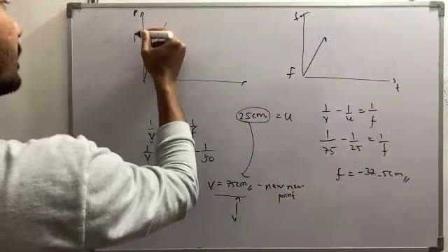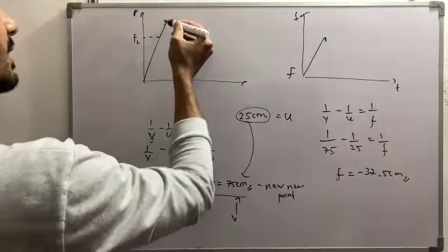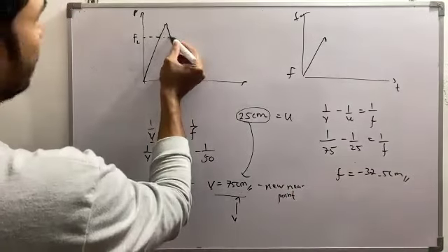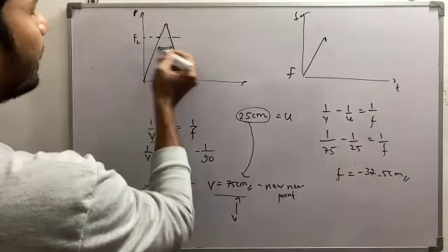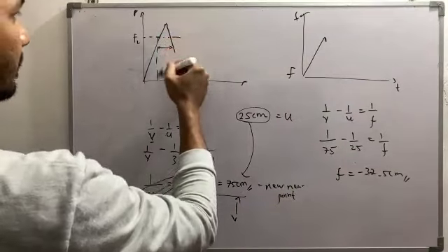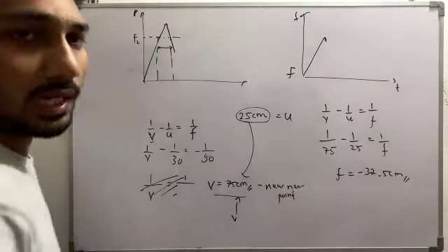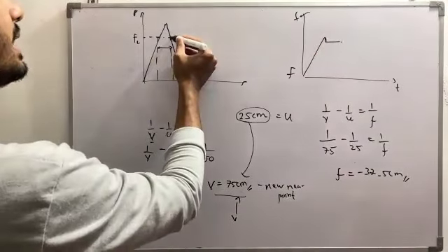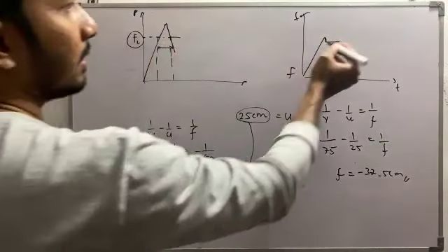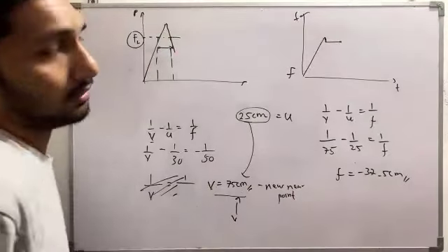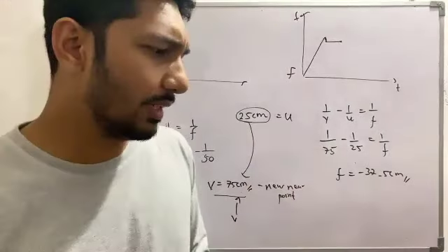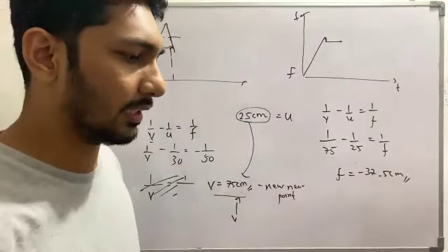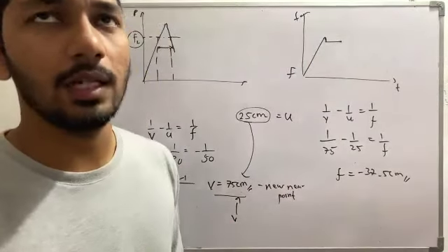So this is the applied force and this is the limiting force. When it increases from limiting, it comes again like this. Whenever it was above the limiting, during this period it will be kinetic. When it reduces to less than FL, then it will stop. Actually, it will decelerate for a little bit of time, and then it will stop.